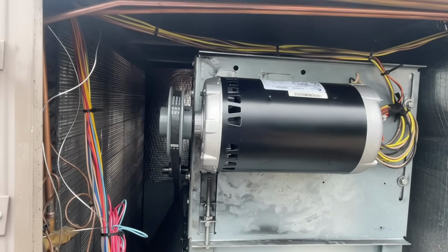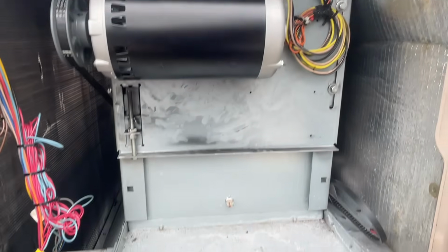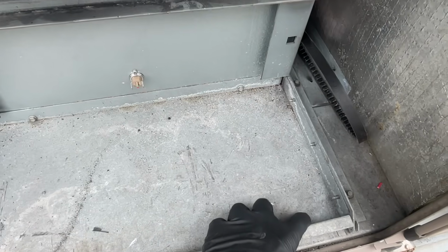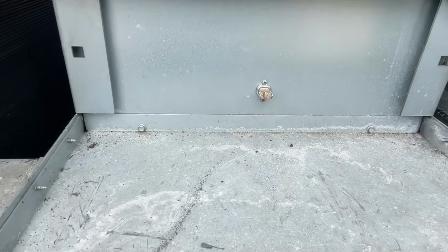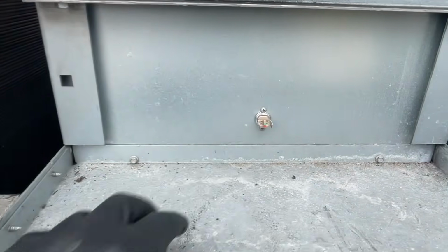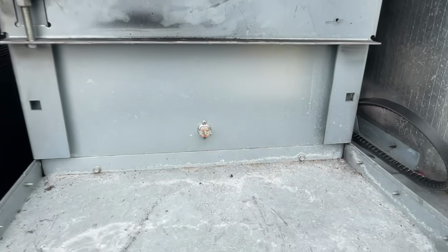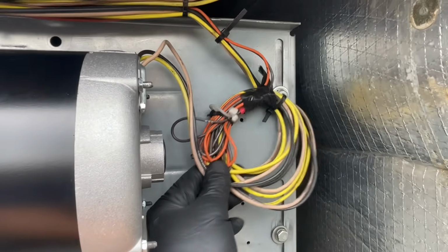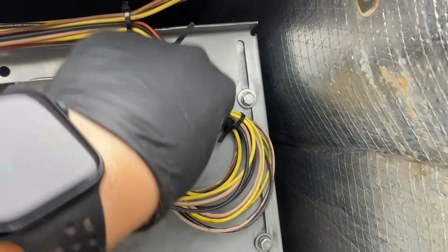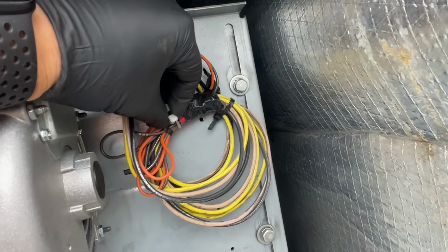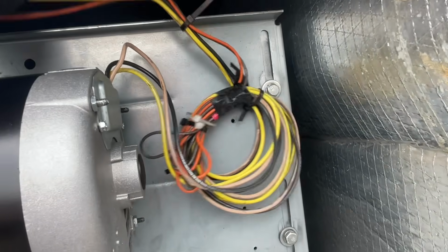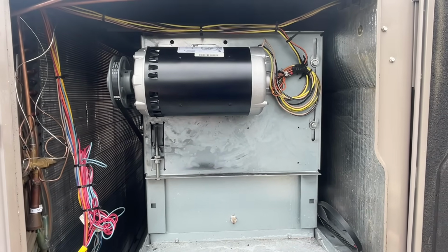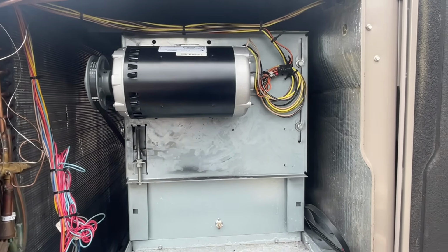That's what it'll look like when the blower's back in place. Our slide's back. We put our 2 screws back to remove our slide. The only thing we have to put back are our high limit wires here, which we pulled off just while we were working on the motor. We've re-secured our power wires here for our motor into this factory little clip York has provided. It's just so they don't get sucked in. We're gonna close this panel up, turn the unit on, and we'll test it out.